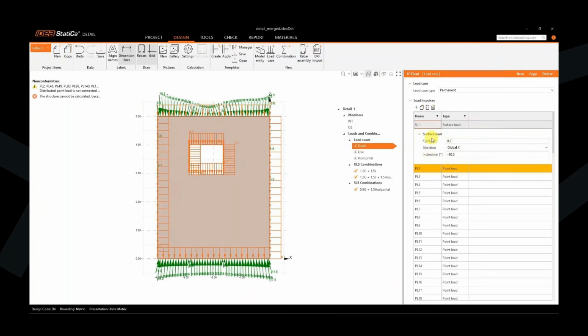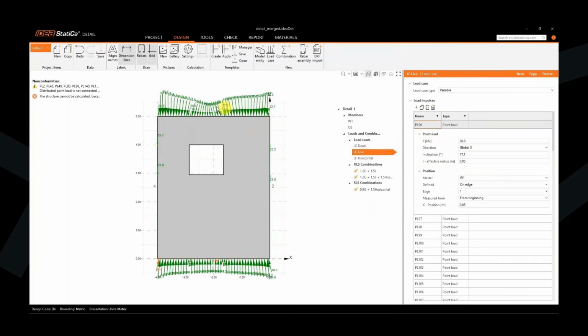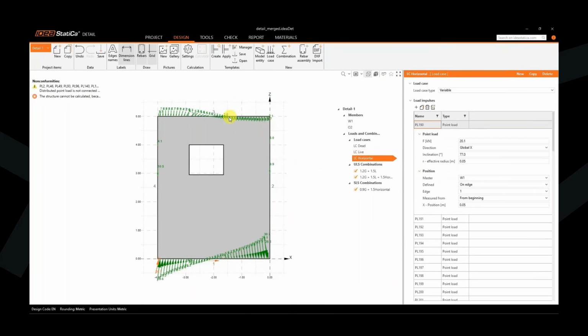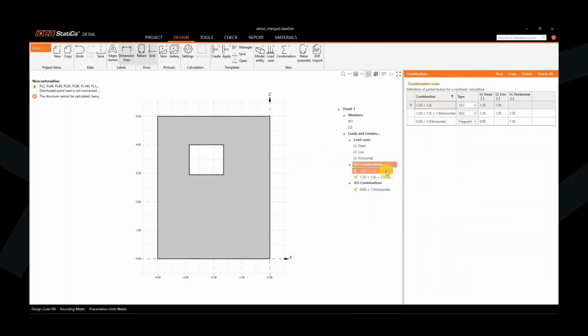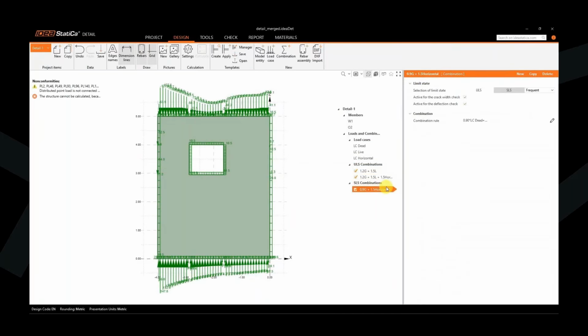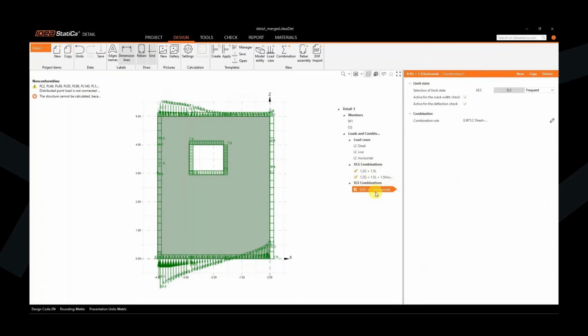Yeah, this surface load is the self-weight of the wall, which is automatically calculated from the material and the thickness from ETABS. Same with the live load. You can also see these internal forces of the wall, and for the horizontal, you can see how there's sort of a moment rotating the whole wall. And the load combination, of course, is automatically transferred again into detail from ETABS.